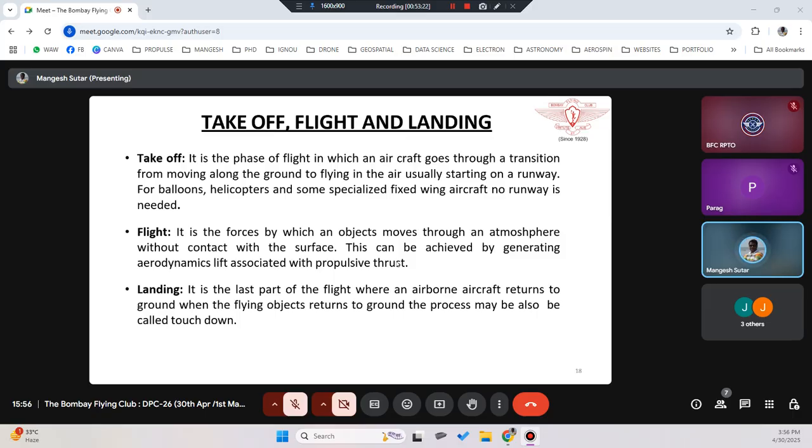Once you have completed your task, you will go for landing. You will initiate the landing procedures, land the drone, and then before handing over or shutting down the drone, you will state the landing status, battery and other parameters. That is called the post check. Even after you power down your drone, you need to check whether there are any damages, stress, cracks, or any physical issues on the drone. That is how you close your activity of drone flying or aeroplane flying.